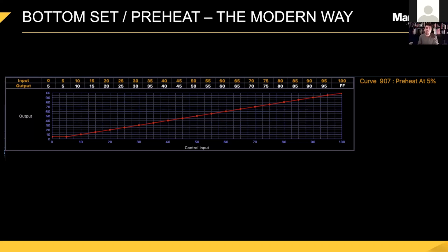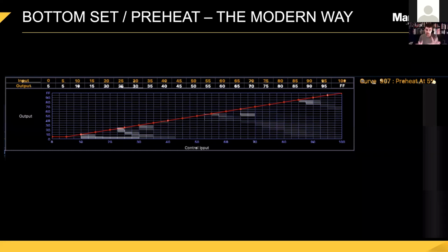It used to be done a lot in rock and roll with par cans when you were doing chases and you wanted the light to appear instantly in the chase. Particularly a tungsten lamp, when it goes to zero and it's cold, the first bit of electricity just has to warm the filament up and get it going before it actually comes to life. It feels like the light is sort of hesitating and then suddenly bursts into life. So this would be a way of dealing with that.